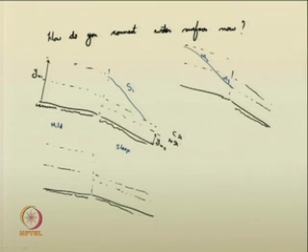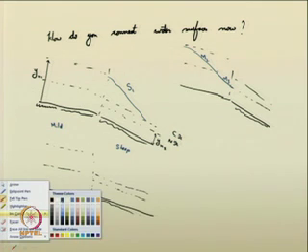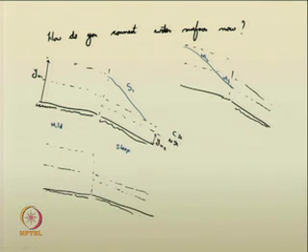In this case, you will see that another possible thing is the curve. It will have an M2 curve in channel 2, then it will have an S2 curve, M2 curve in channel 1 and S2 curve in channel 2. Like this, a water surface profile may exist. So, which among them is correct?